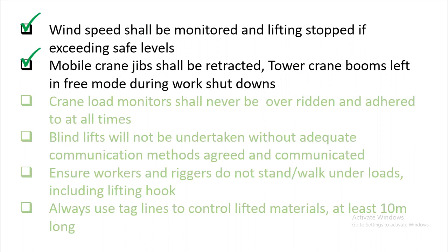This is in case there is an increase of wind speed. With freewheeling, the tower crane booms will not collide with each other. They will just follow the direction of the wind.